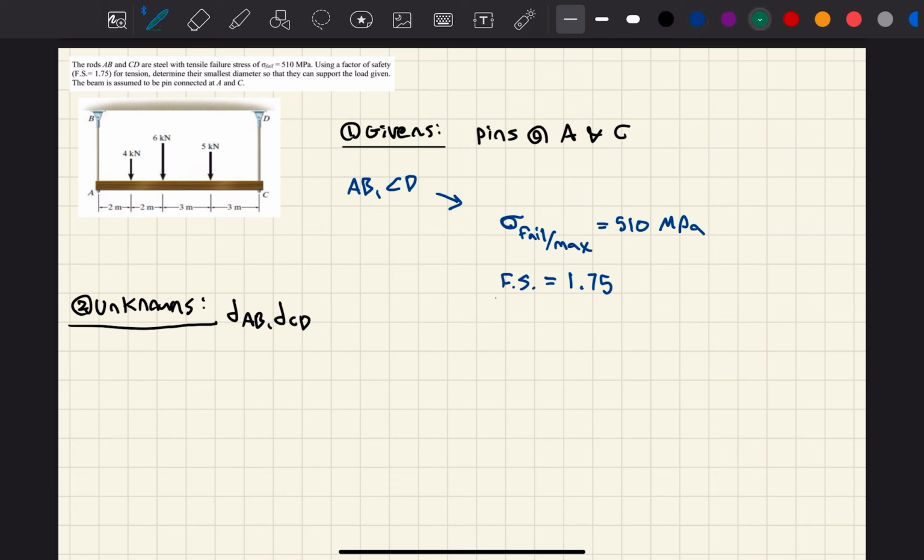Well, the definition of the factor of safety is the ratio of the maximum stress a material can handle over the allowable stress, or the stress that is normally applied, basically the stress that a material will normally encounter. Why does it matter? Should this number be up or down? As this number increases, it gets safer, but other things like cost and weight and testing come into play. You can't just make everything as safe as possible.